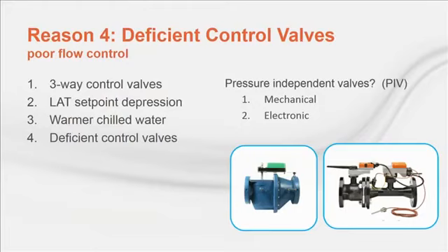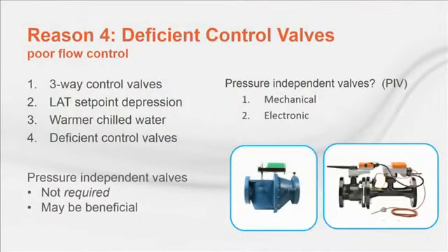Both can work equally well, and each has its own set of advantages. The question is, are pressure-independent control valves needed to assure good system delta T? This is a question of much debate among engineers. My answer, no, they are not required to get good control, but they sure do make it a lot easier